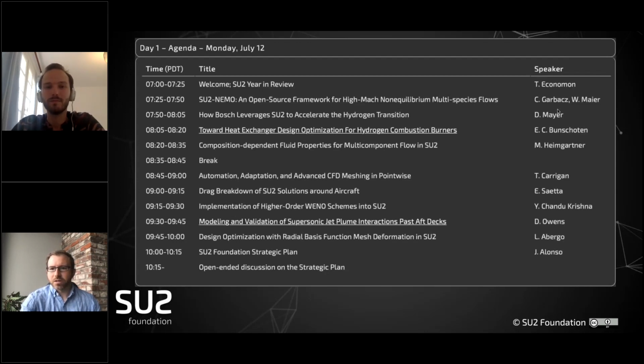So another question is, what is the limiting factor of SU2 for better computational performance with respect to Fluent? I guess for your results here. Yeah, so the residual of the scalar still stays very high. So I should look into the convergence of the scalar solver, and that's probably the main thing I would say.